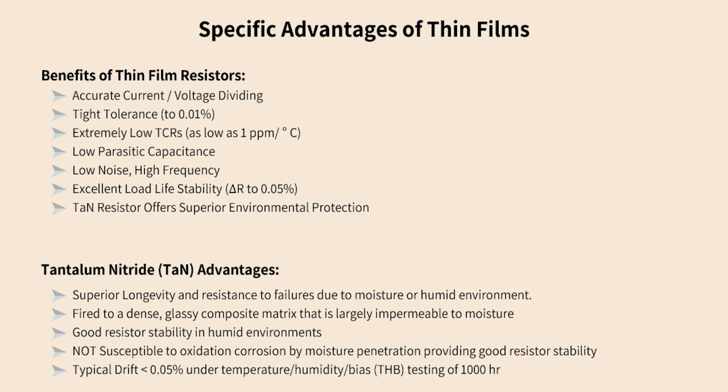Within thin film technology, tantalum nitride provides additional advantages, especially in challenging environments. Tantalum nitride resistors are highly resistant to moisture and environmental stresses due to their dense glass-like composite structure. This makes them particularly well suited for humid or corrosive conditions where other materials might degrade. In long-term testing, tantalum nitride resistors show minimal drift, less than 0.05% after 1,000 hours of temperature and humidity exposure, highlighting their longevity and stability.